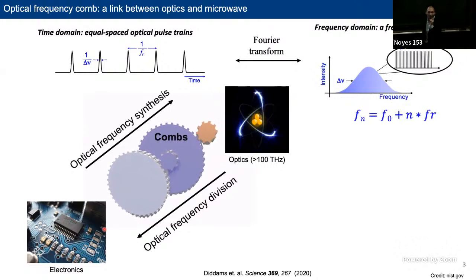And from the other side, from radio frequency to the optical frequency, we have a lot of very low phase noise and reliable radio frequency sources right now that are commercially available on the market. You can take advantage of those devices and, for example, take the radio frequency source as a modulation driving signal to drive a single frequency laser, and you can generate an arbitrary, or we call it, electro-optic frequency comb, which I'll be discussing in the first part of my thesis defense.